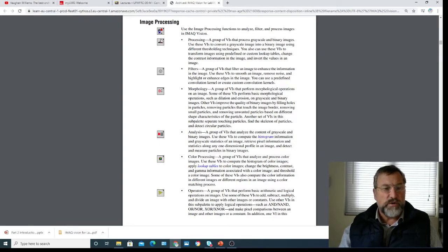With this, suppose you've got the laser, you turn the laser off, you can turn it on and off at high speed, take an image, and then turn the laser on and take another image. And then you subtract the first image from the second one. This gets rid of the background light. The reason it's so good is that no matter how much the light's changing, if you do that quite quickly, it will remove the effects of the background light. You'll see the laser line clearly, and that is very good. The only time that wouldn't work, of course, is if the background light got so bright that it overexposed the image. But other than that, that's a very powerful technique for dealing with changes.